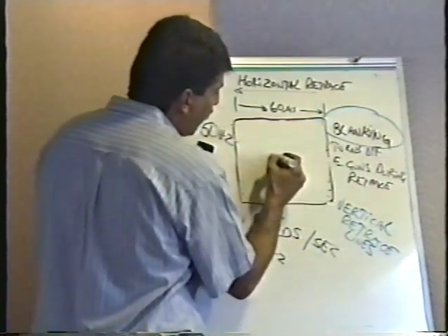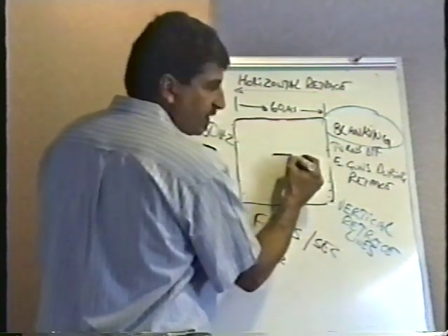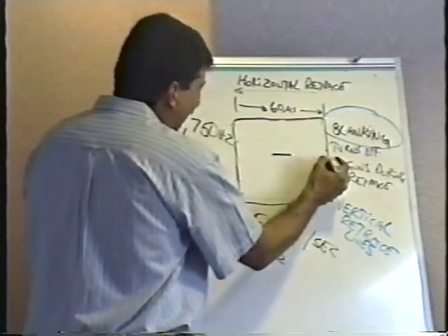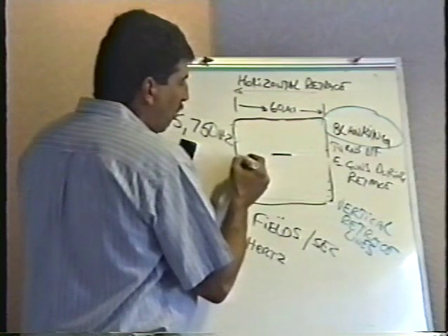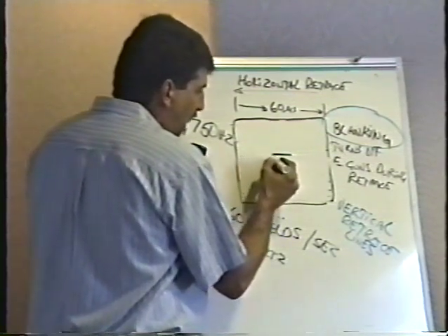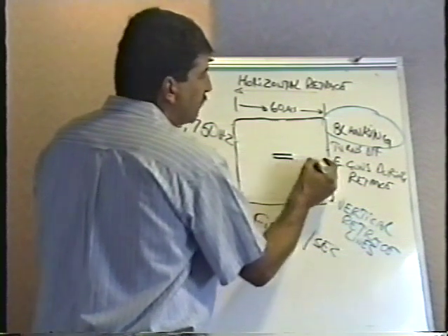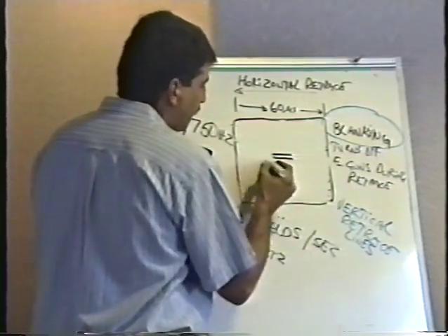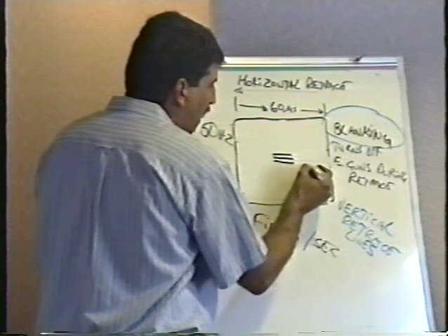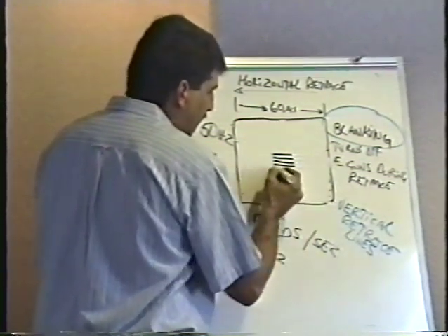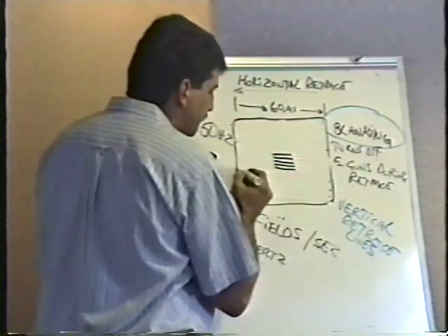Or when it wants to start drawing the box, it turns the beam on and draws a line. Turns off, goes to the end, has to go all the way to the end. Retrace, off. When it gets underneath the first line, it draws the second line. Turns off, goes to the end. It's off, on, off, off, off, on, and so on. Now, of course, the lines are a lot more closely spaced than this.